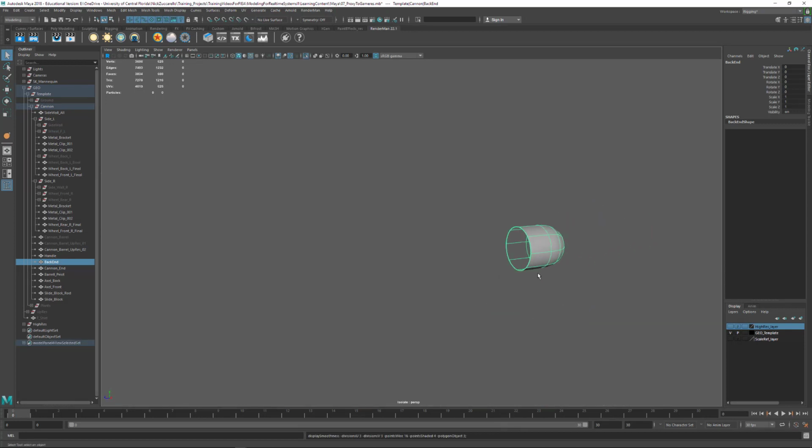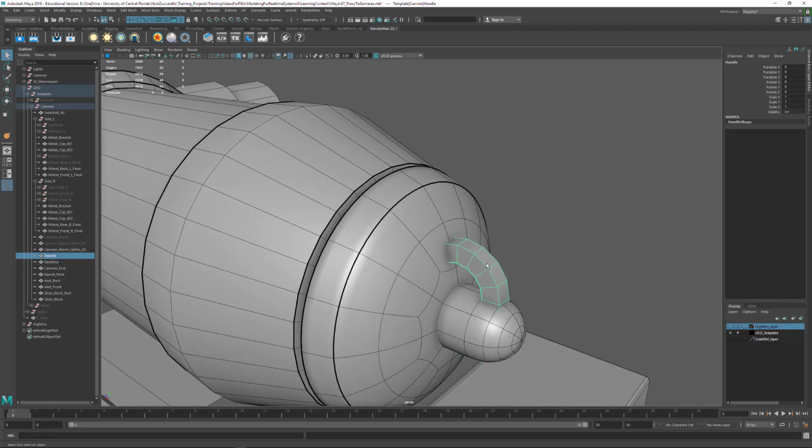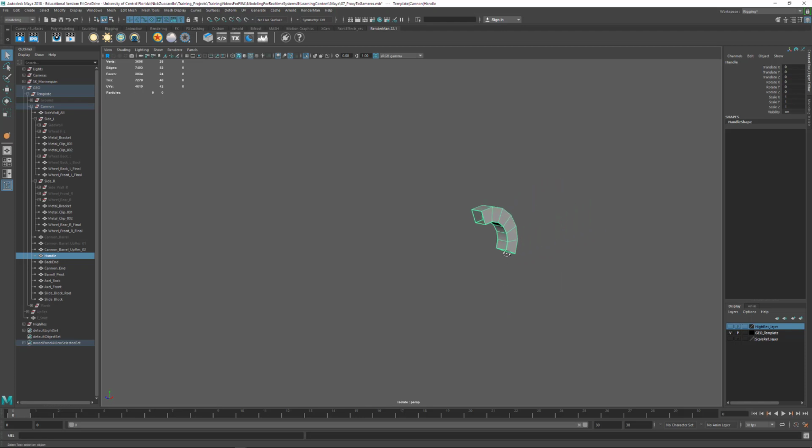Now if we tap 3 for this one, since I don't have a face on the end of that, it should make this nice and smooth. So I can hit Control 1 for that. So on this shape here, we'll select it, and then we're in object mode, Control 1. And I don't have the end pieces there, so I'll just tap 3. And you can see how it rounds out. I want to keep this nice and crisp for these edges here.